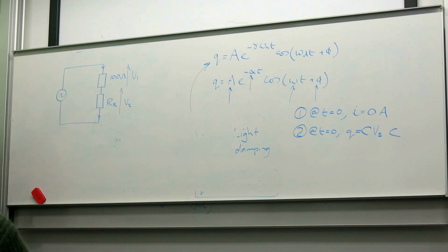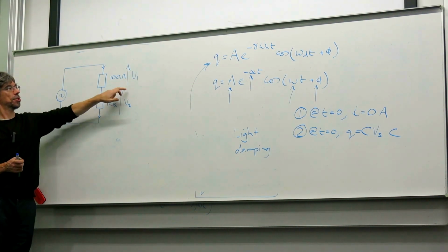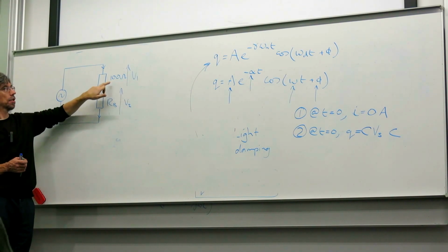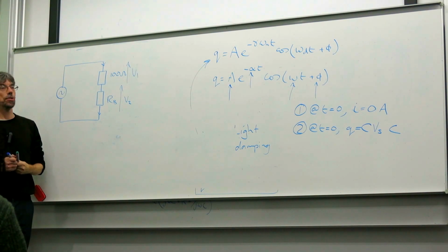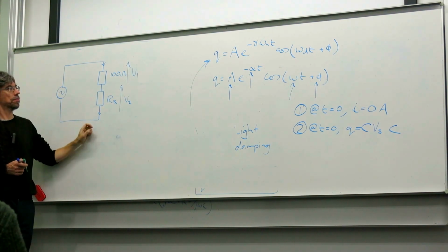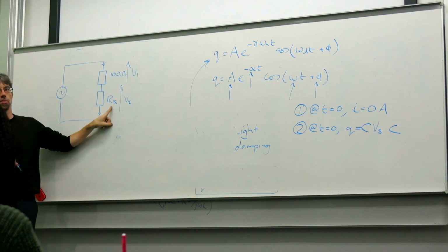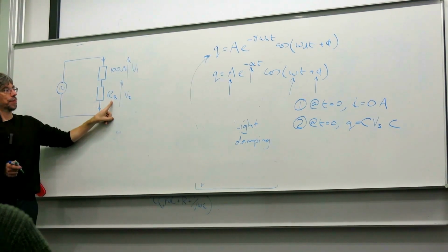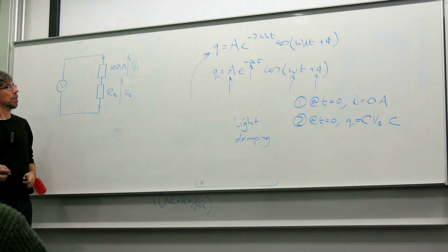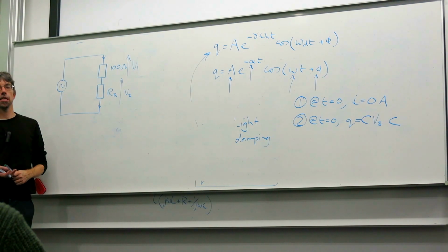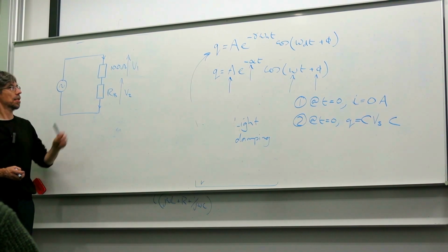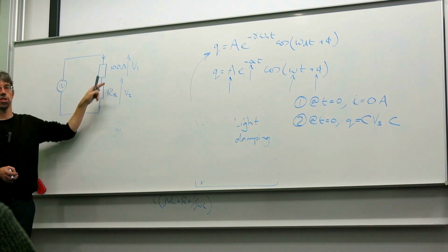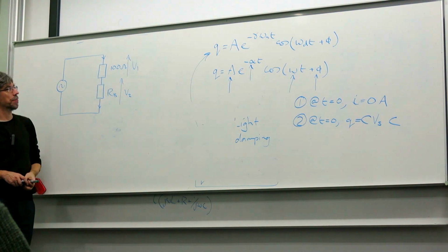But on your oscilloscope, what you might find is that at high frequencies, the voltage across the 100 ohm resistor is slightly out of phase with the voltage across the resistor box, even though the resistor box itself is set to 100 ohms. So that implies that something is causing a phase shift in the circuit when we compare the resistor and the resistor box.